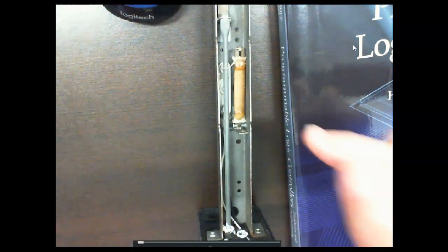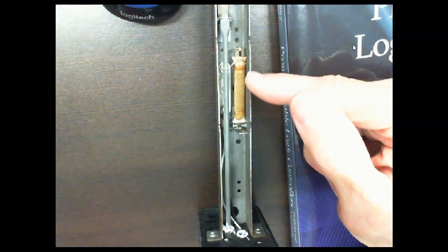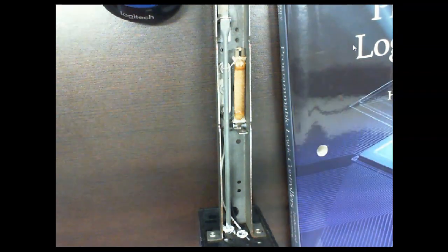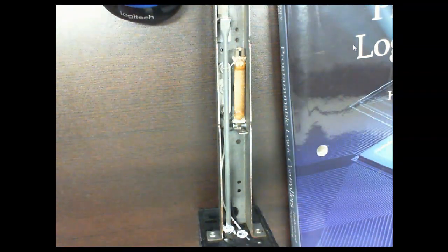Yeah. So this is an RTD right here. Normally in industry it'll be encapsulated inside either a metal tube or a ceramic tube. But all it is is a bunch of fine gauge wire wrapped around a ceramic rod. They put a voltage across it and it changes the current. Its resistance goes up with temperature. And they're very, very rugged. These suckers will last forever.